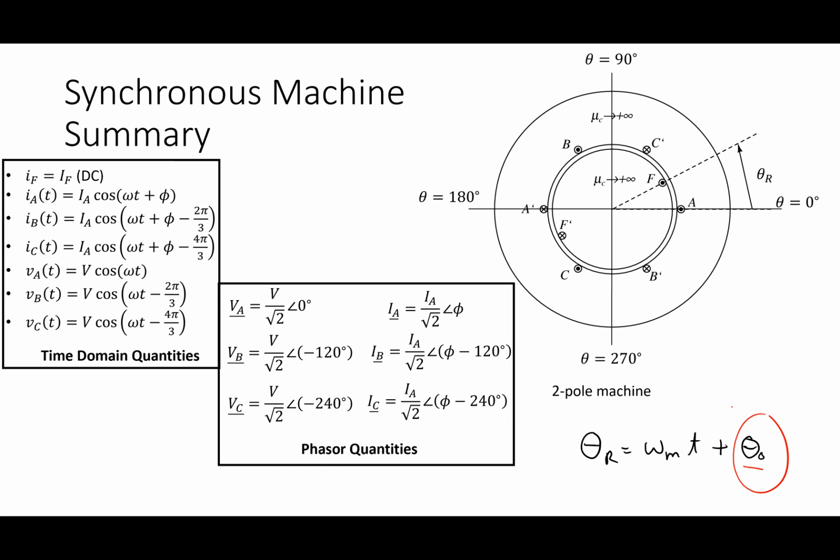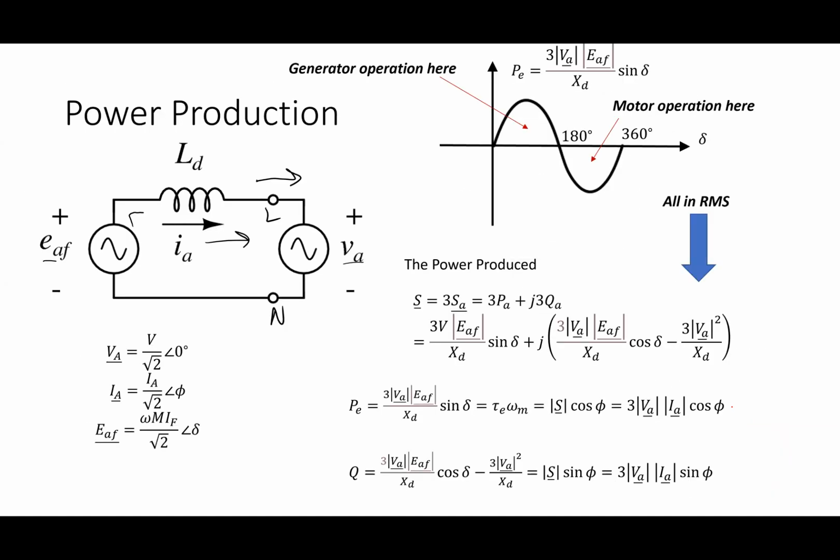It's a fundamental principle that the machine operates in synchronism with the grid. When we talk about issues of the grid being unstable, that's really when those machines are losing synchronism with the grid, which can happen. Typically, it happens because there's a short circuit or some sort of funny phenomenon going on on the grid side. And you're looking at that in problem one.